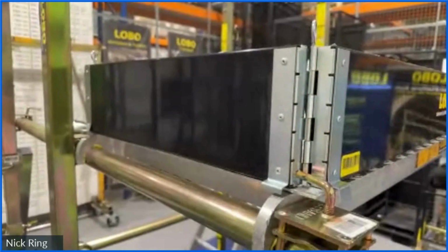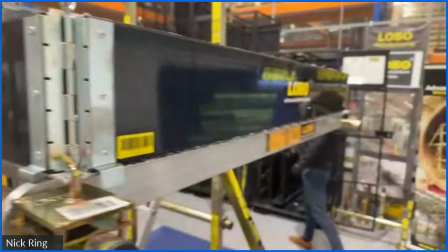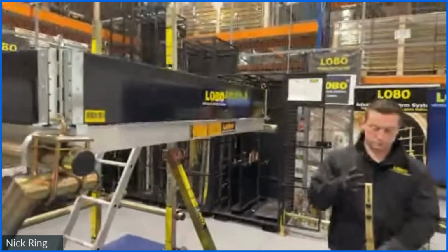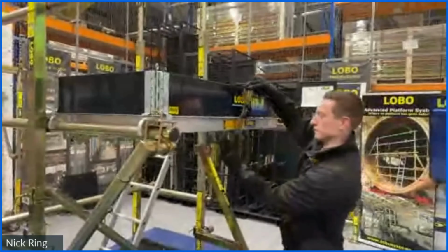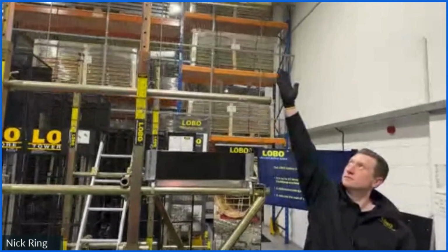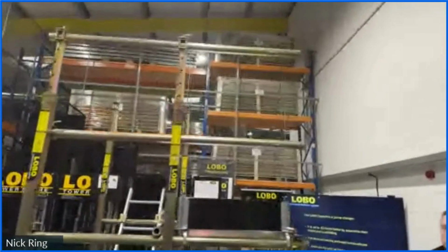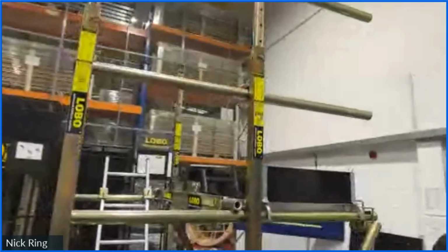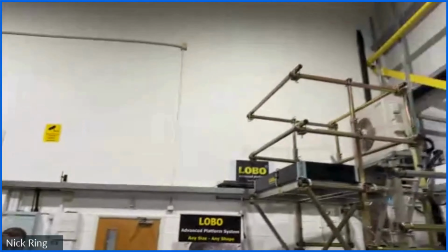And finally, we're going to put on a toe board clip. So put a few of these on to lock that toe board down whenever you want, wherever you want. Now, this tube here that Nick's now pointing at, and the one above, are your guardrail system for when you're working in the cantilever area. This is what it needs to look like.